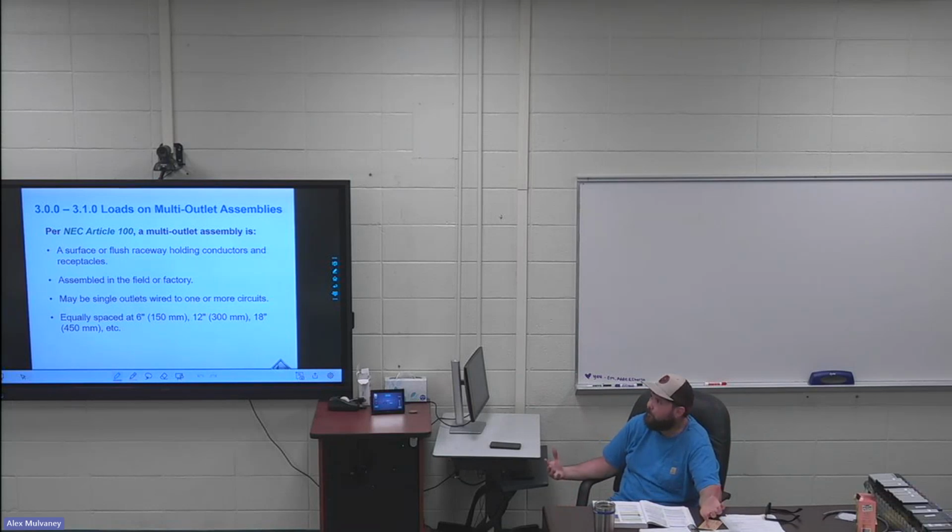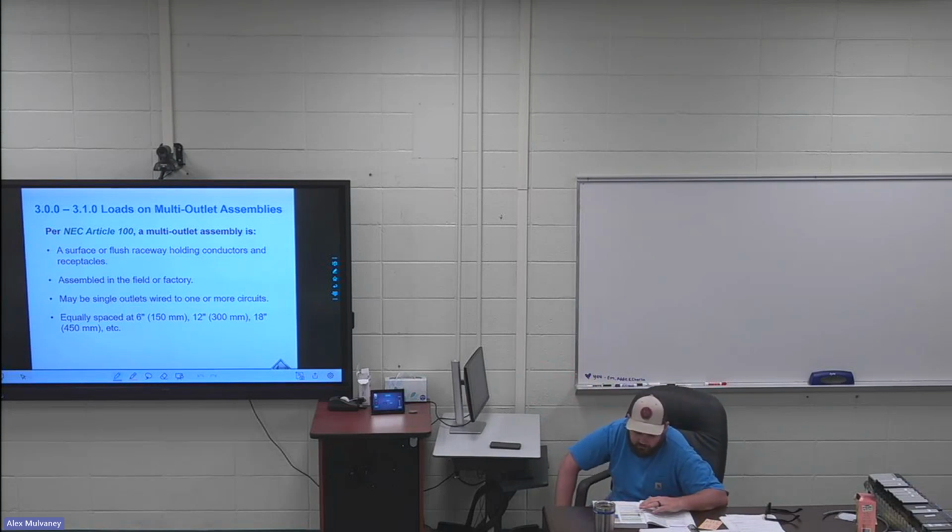A lot of people want more than that, but everybody's seen the open signs, like you pull the string neon sign that says open. That's what that's saying. So people don't run extension cords to their neon signs. The code is requiring that they put outlets in places like this.